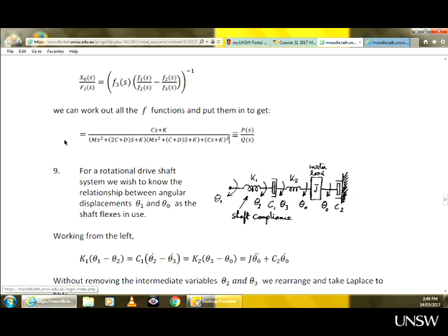What is the order of this transfer function? The order of a transfer function is equal to the order of the polynomial in the denominator. Here you have s squared multiplying s squared, so the highest term will be s to the power of 4. So this will be a fourth order polynomial and therefore the fourth order transfer function. How many time constants, at least in theory, are we going to have? 4.